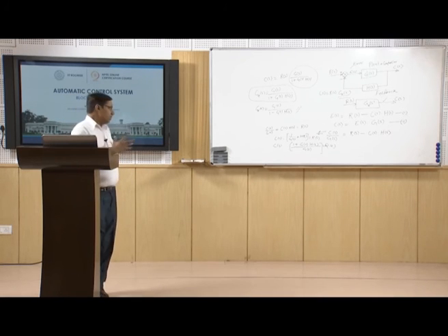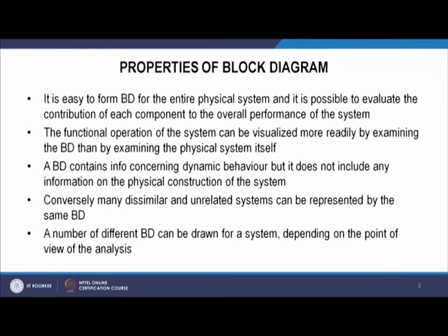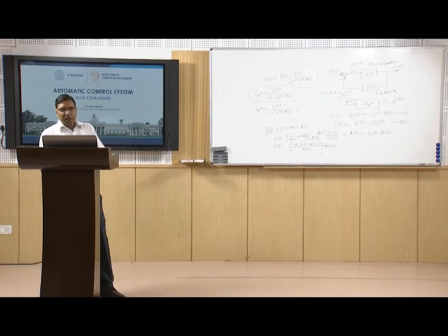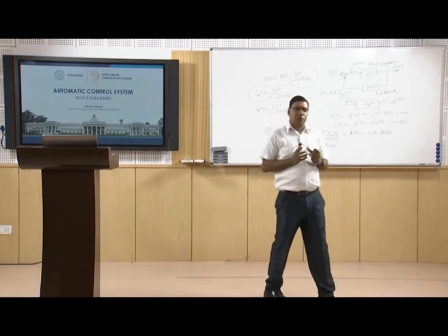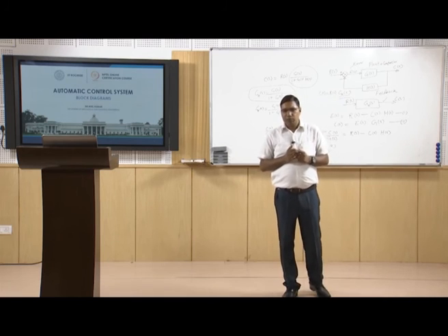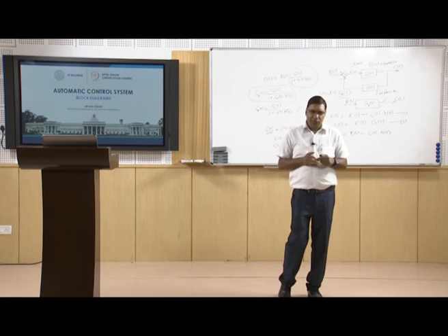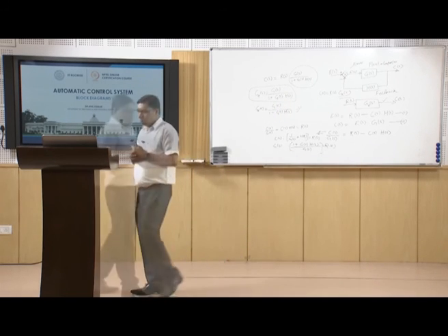What we see from this is that it is easier to make a block diagram for a physical system, and we can evaluate the contribution of each component to the overall performance of the system. By examining the block diagram, we can examine the parameters of that system, because the block diagram consists of the transfer functions, which contain the properties of the system.